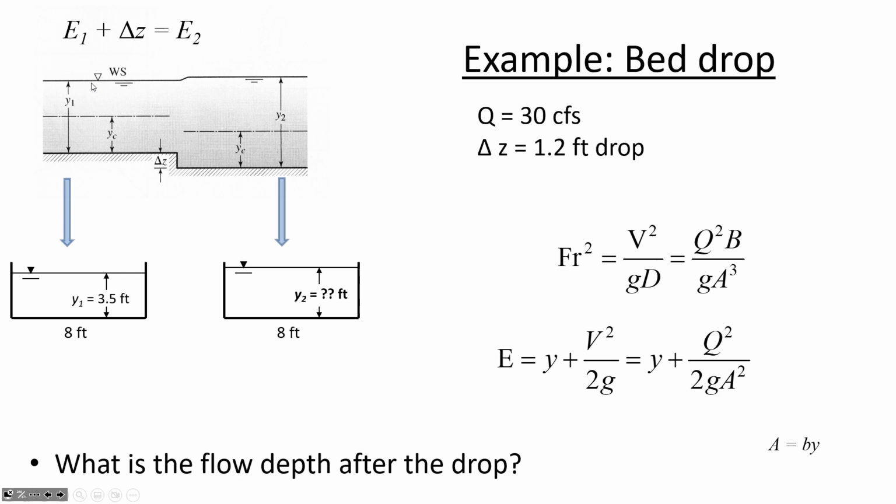And that's going to be important because we're going to be solving a cubic equation. We'll have one negative root, and then we'll have two positive roots. One of those roots is associated with the alternate depth that is supercritical, and one is associated with the alternate depth that is subcritical. We have to know which of those two roots to select. This first part that we've done in diagnosing the flow regime is going to tell us which of the roots to select once we have a solved cubic equation. Okay, is everybody okay with what we've done so far in diagnosing the flow regime at 1?